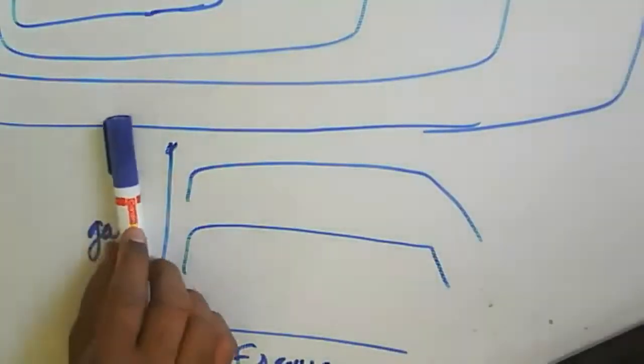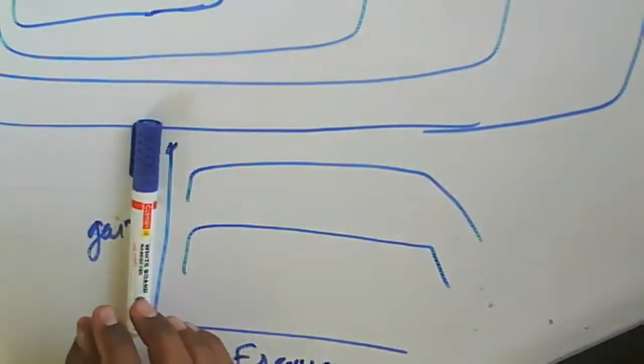So we can conclude here that the multiple delay line canceller, or n pulse canceller, or transversal filters, or recursive filters, all work as time domain filters rather than frequency domain filters. And generally, in a Doppler filter bank, a time domain filter is chosen.